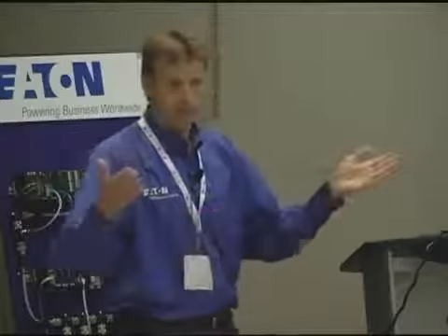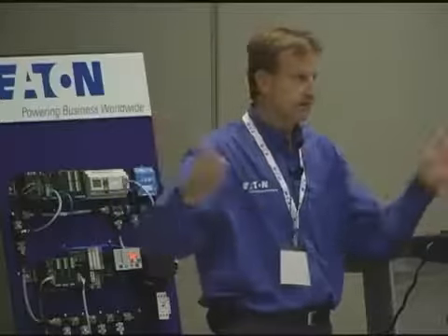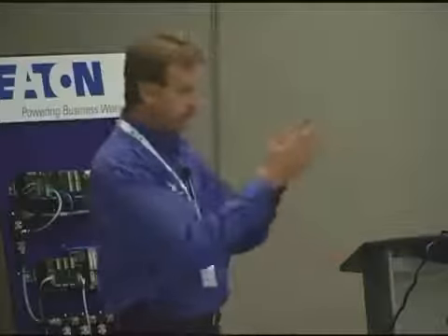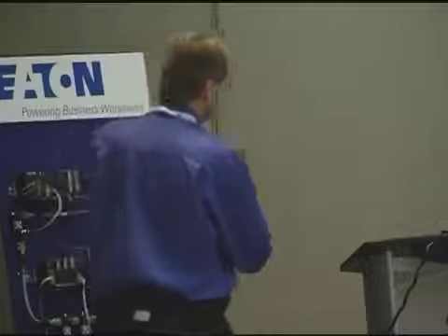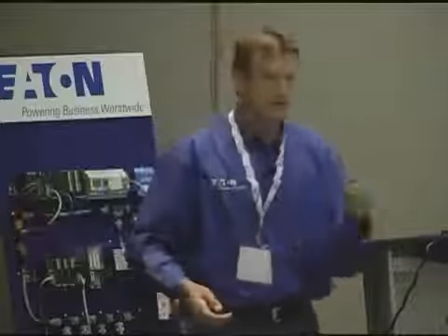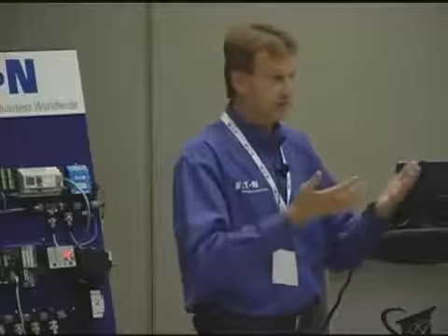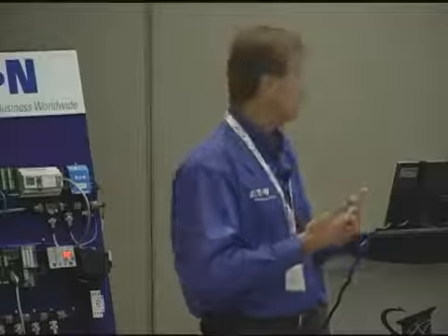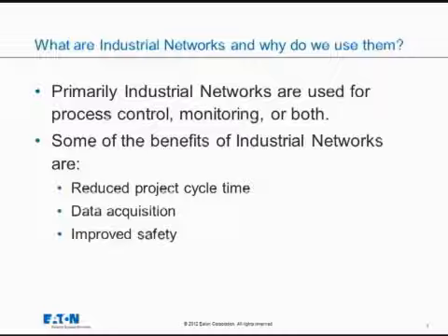So now your project cost just got higher because now you've got a PLC rack with lots of cards. As to compare it now, we've got a PLC rack with a network card. So we've saved some money there. Data acquisition: instead of wiring your signal to a PLC, now we just ask for it, because these products using network protocols have data available to you at any particular time. So it makes data acquisition very flexible to ask for different types of information.